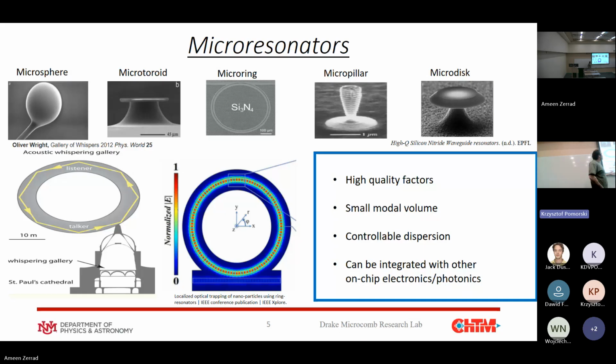So that's the idea. We deal with microring resonators. They can be many different materials, but we leverage silicon nitride because we're interested in four-wave mixing. We want high quality factors so that we can build up a lot of power in the cavity. You're trying to generate light through nonlinear processes, and nonlinear processes require a lot of light. I'm going to talk more about that later.